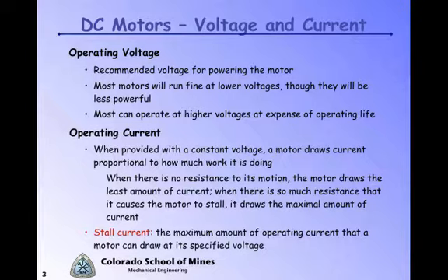The thing that really kills DC motors is heat. The heat causes the insulation between the winding loops to break down, and once you have that breakdown, you have a short, and then you get much larger currents flowing, and then you get more heat, and the motor is dead.